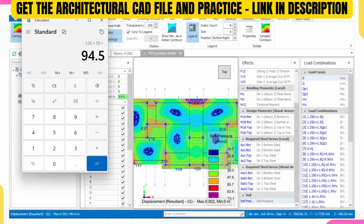That's why we use 1.35. If you're using British code, you use 1.4. So the highest load the soil can carry is this 94.5, while the highest load this structure will transmit to the soil is this 72.1. With this, that means the soil will be able to carry the load coming from this structure perfectly.